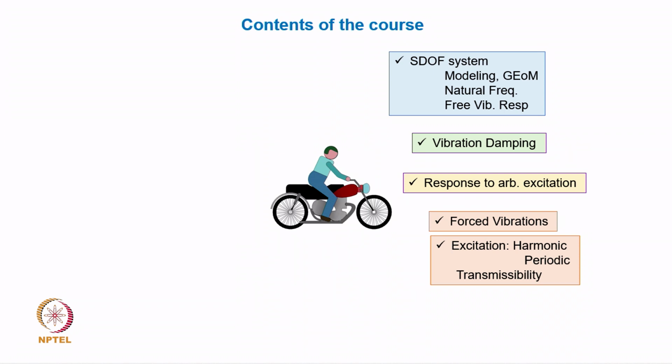The excitation could come from a force acting on the inertial mass, or the force could be through the base excitation or a base profile or a base motion. In either of these two cases, we explored how the response is obtained for a given excitation frequency.